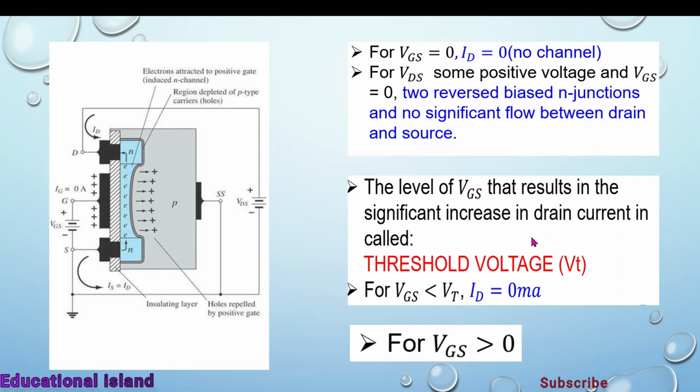At these voltages, the device starts working when VGS is less than the threshold voltage, then the value of drain current will be 0. And when we apply VGS positive, the electrons will be attracted from the p substrate towards the n channel, which is induced after biasing. Then electrons go from source to drain, because we have already applied VDS here, and the drain terminal attracts the electrons from the source. Through this mechanism, conduction will occur in the E-MOSFET.